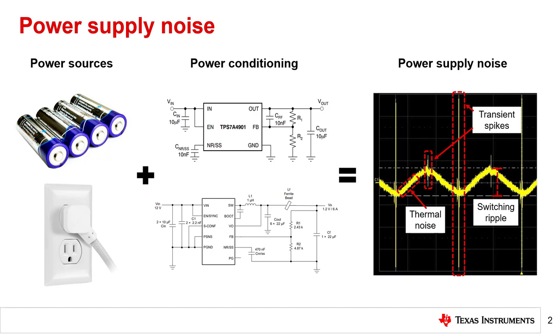In addition to power supply conditioning components, AC noise can originate from other switching components that use the same supply, such as clocks and clock buffers, as well as from ambient lighting or other environmental elements. Ultimately, the ADC power supplies will likely have some combination of both thermal and switching noise regardless of which power source is used. However, since power supply noise is external to the ADC, semiconductor manufacturers can only specify how effective an ADC is at rejecting this noise. This specification is called power supply rejection ratio, or PSRR.